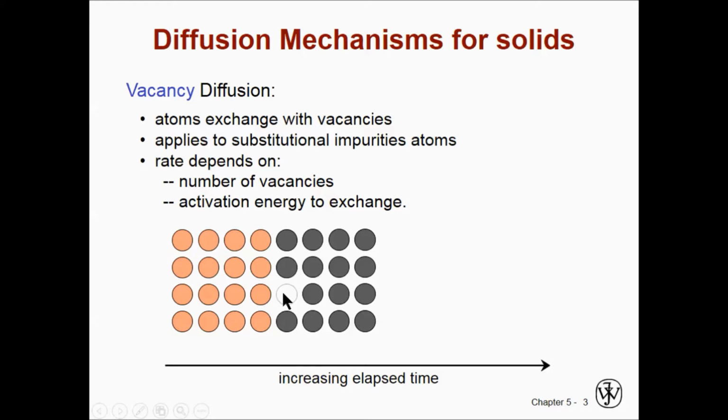If enough temperature is provided, this copper will diffuse into nickel, so this copper atom will occupy this vacant position. So if you see here, the vacant position moves when atoms move. So this is actually, if you remember, a substitutional solution.